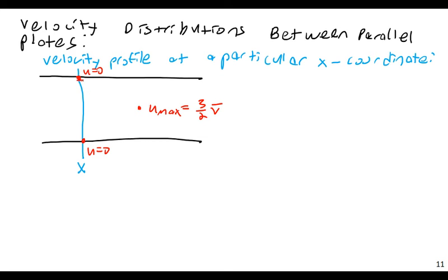And then we would have a parabolic relationship developed kind of like this. All the way along here, at any given height, or at any given distance from the center, you'll have a different x velocity. And I apparently can't draw parabolas. But somewhere along the line, you would have a v bar. So at a particular height, you would actually have the average velocity. It is really just the integration, or the mean value theorem applied to the u distribution.